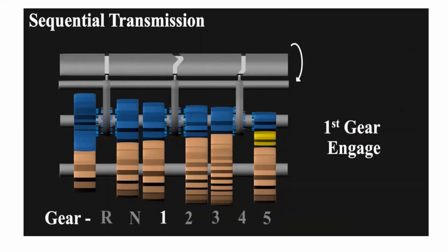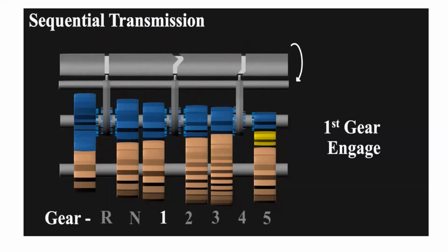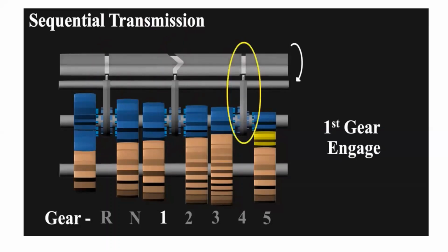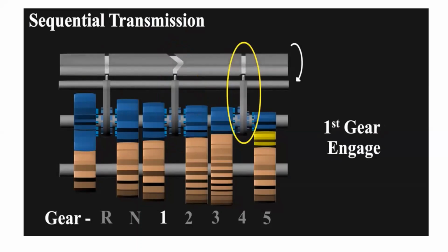One thing to note here is that when one gear is engaged, the other grooves make sure that the forks are in position of disengagement from the other gear sets. The grooves are designed in such a way that, after a specific degree of rotation, the gear selected earlier disengages, followed by the engagement of the next consecutive gear selected. The same pattern follows for downshift. These grooves ensure that, before shifting to another gear, the previously selected gear is disengaged.